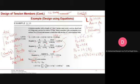Now what we are going to do is check whether the gross area of this member is greater than this or less than this value. So the gross area, we know that for this member the gross area is equal to 3.23 inch square. Now we will calculate the net area. How can we calculate the net area? We will subtract the area from the gross area. No, this is not the gross area, I'm sorry. For this one the gross area is 3.5 inch square, I'm sorry.